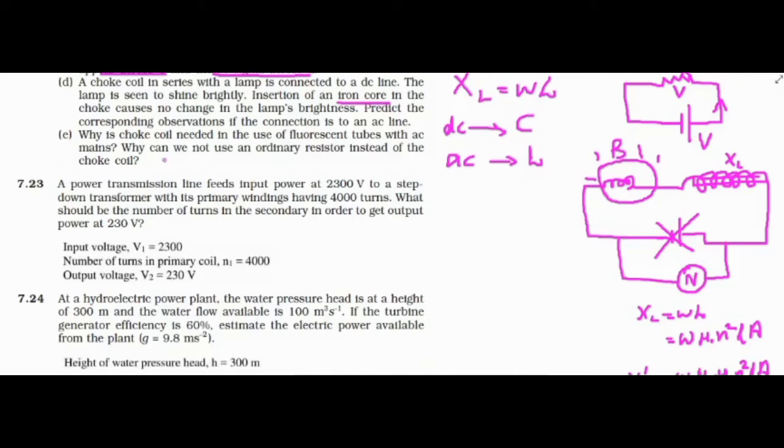Okay, so we need a very high voltage to excite these atoms. So high voltage electric discharge is required. So how can you produce high voltage there? High voltage can be produced with the help of choke coil. Okay, you can control the current so that you can increase the voltage.